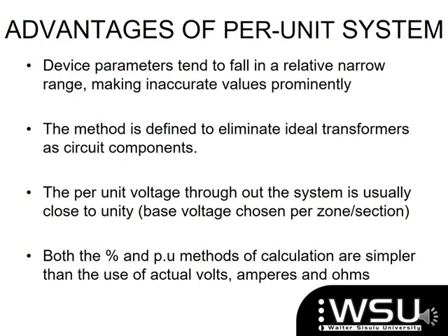If your line is exactly the same as the transformer voltage, in other words, it's an 11 kV line and your transformer was stepping down to 11 kV, then obviously your base voltage would be unity because it would be 1. But if, for example, on your generator, as we like having generation, your generators would usually be about either 13.2 kV or 13.8 kV. But your transformers are standardized at 11 kV, stepping it up to another voltage.